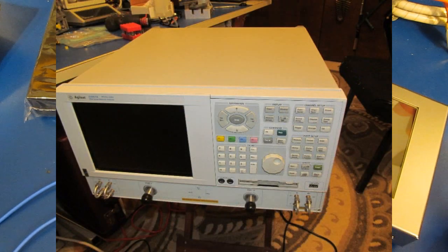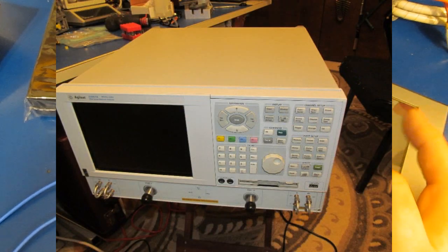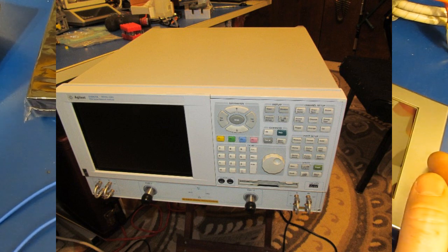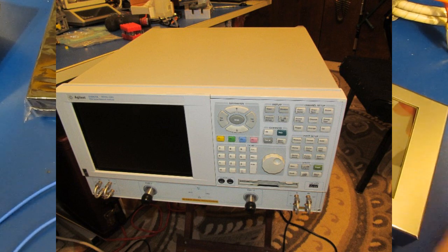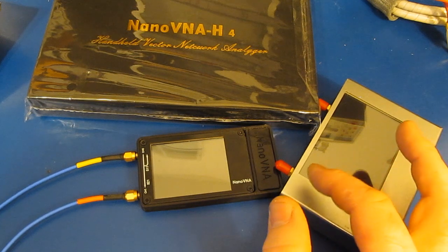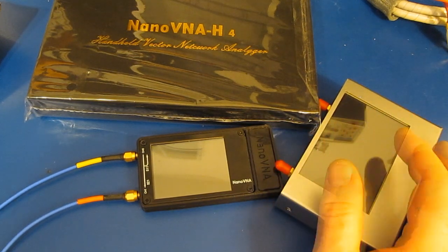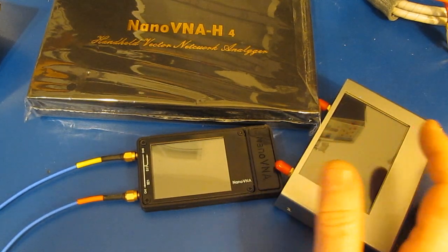I also own a newer Agilent VNA. It actually has a pretty good noise floor and the dynamic range is really good on it. The problem with that network analyzer is the lower end is limited to 300 kilohertz. Again, that's far too high to be used to make these measurements. On the high end though, those network analyzers will run all the way up to 3, 6, or 9 gigahertz, so that's well above what we would need to measure our PDNs. So unfortunately, out of all the network analyzers I own, none of those are really suited for making these measurements.